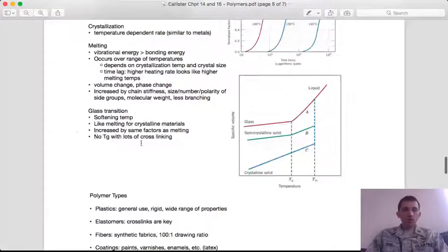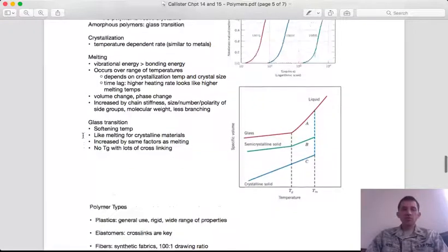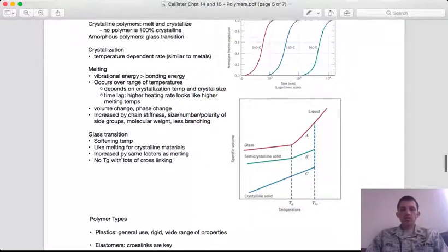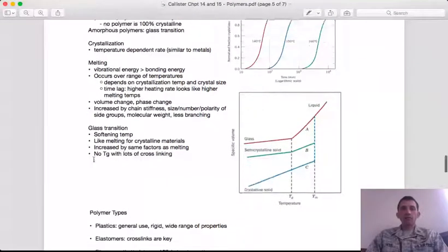The glass transition temperature is typically most pronounced in thermoplastic polymers, meaning ones that don't have cross-linking. As you add more cross-linking, the glass transition temperature character tends to diminish to the point where it might actually appear to go away completely, because with many cross-links, it doesn't really matter how hot the material gets, how much energy is available for the chains to move with respect to one another.